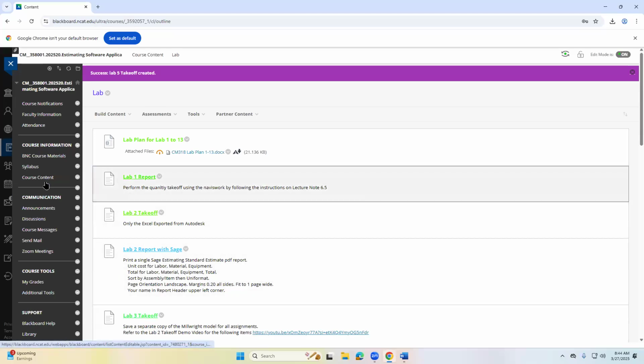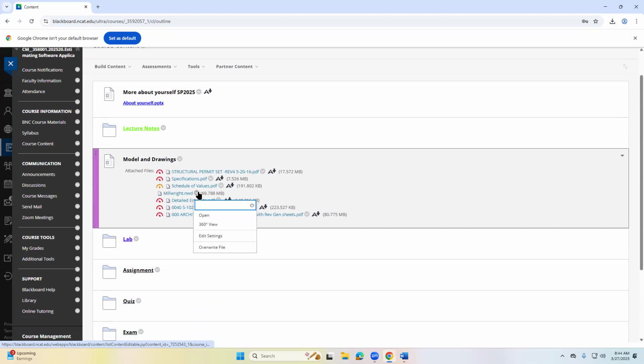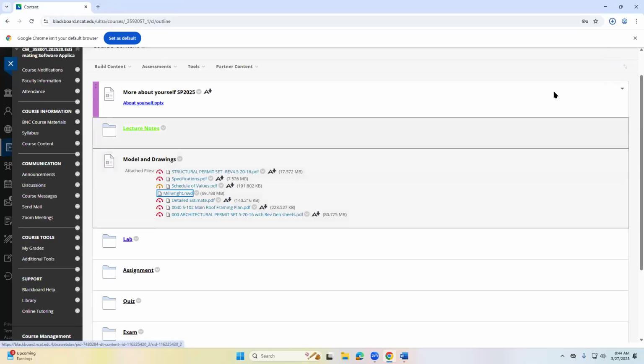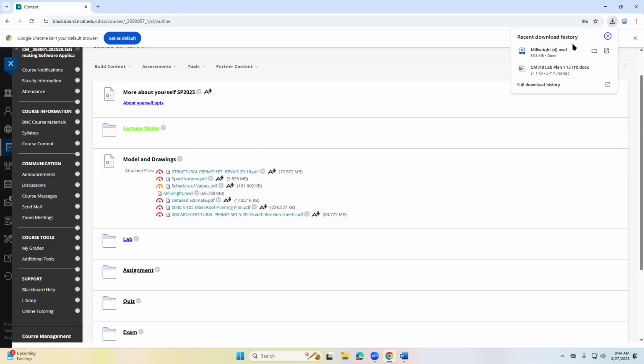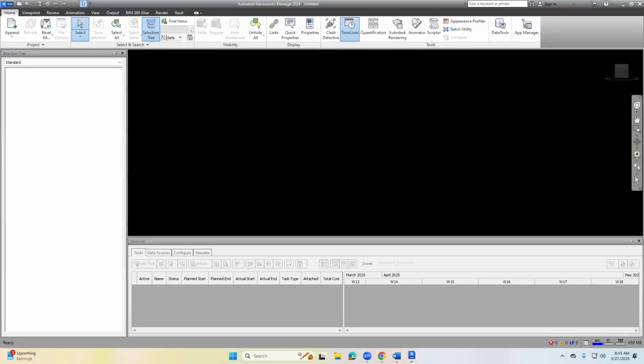So we can go to the Blackboard and find all the course content, and also download the course module here. If you don't download this one yet, you can click it to download, and then you can find it here. This one ends with NWD. That basically is a Navisworks file, so you can directly open it in Navisworks. We can double click this one, and then Navisworks Manager will be opened in seconds.